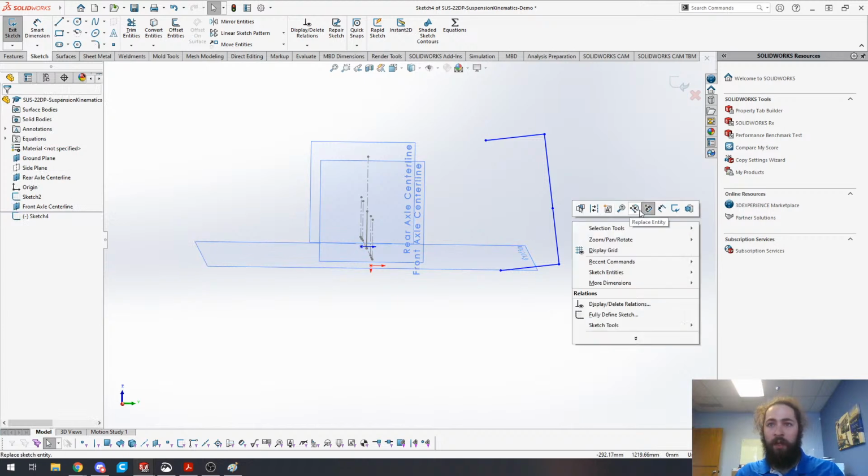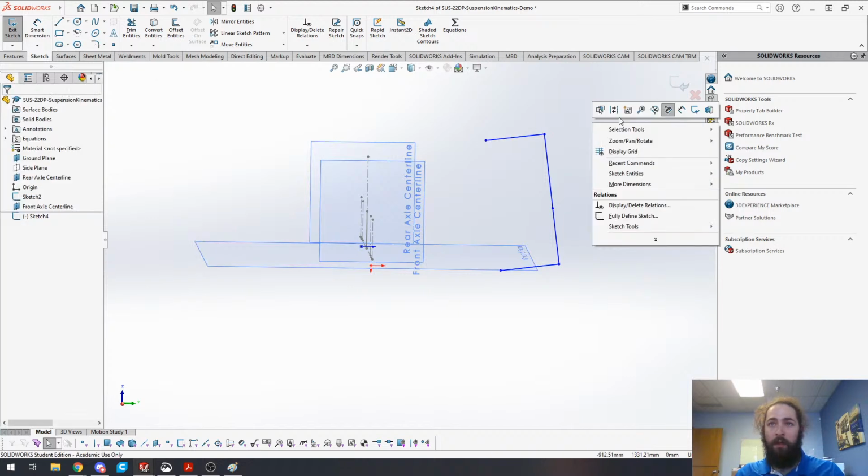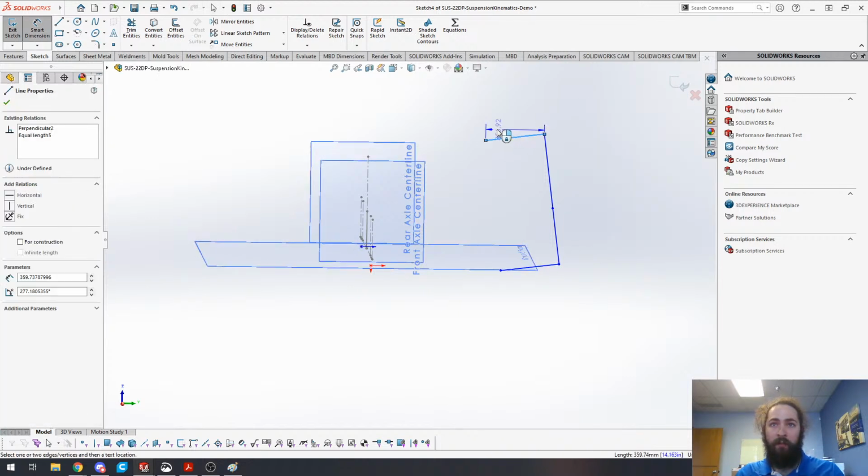And then we'll start setting some dimensions. Actually, we'll also set both of these to be the equal length. And we're going to dimension this top one. And also be careful of this dimensioning as well. This is partly why, again, the static camber here in this case is going to be 1 degree. This is a lot more than 1 degree.